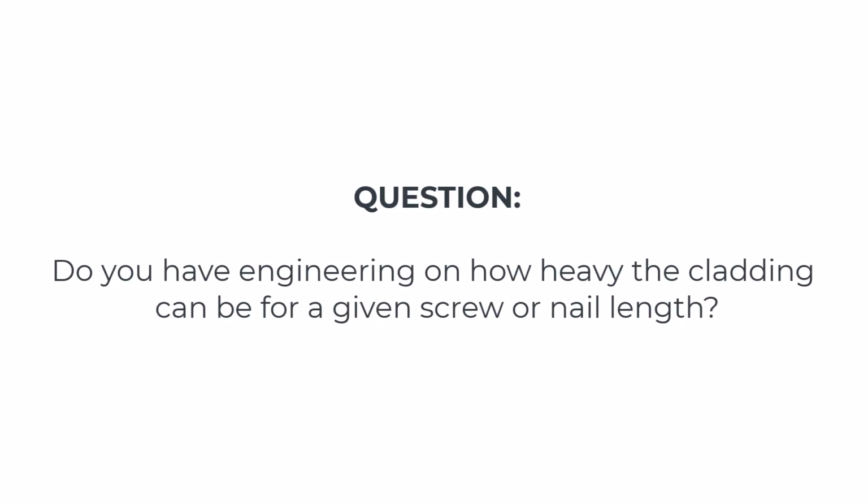Do you have engineering on how heavy the cladding can be for a given screw or nail length? That's already built into the code. It was something we foresaw coming back in 2010 or 2012 with the energy code changes. So there was a lot of research with NYSERDA and DOE, the steel industry. I worked with the wood industry, the insurance industry, and we put together a lot of testing to look at how much a cladding fastener can take with this thick of foam or that type of foam, and what the limits are to doing that.